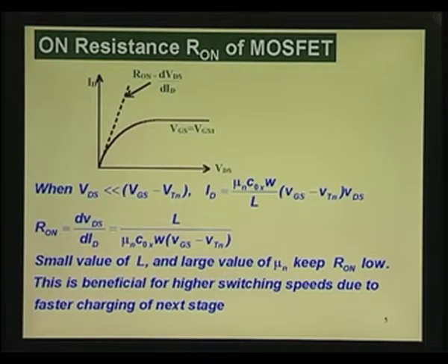Now, what we saw in that series, that resistance R which was coming at the input, which decides the cutoff frequency, is actually the on resistance of the previous device. So, now let me tell you what is on resistance, I have put this diagram here. This is the output characteristic of the MOSFET for one gate to source voltage Vg. Okay.